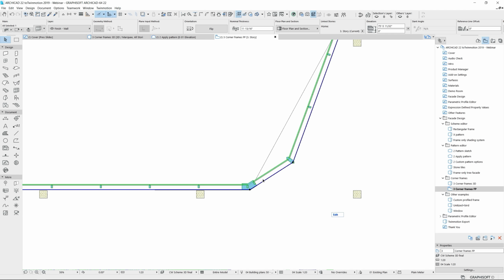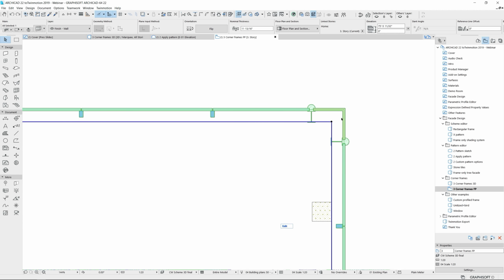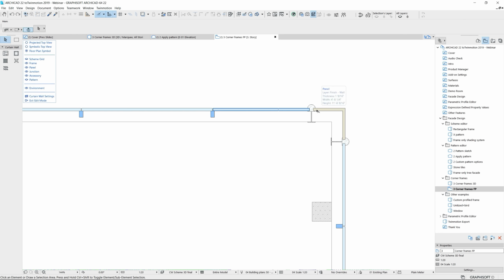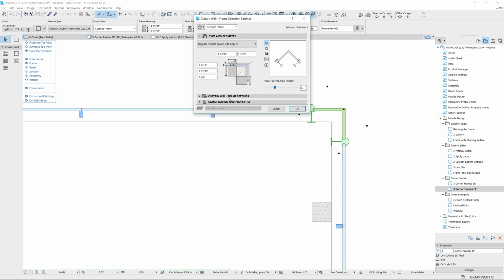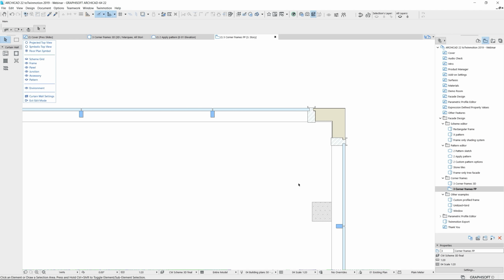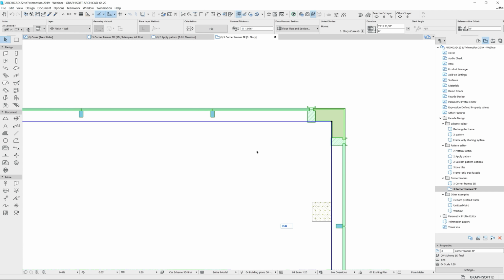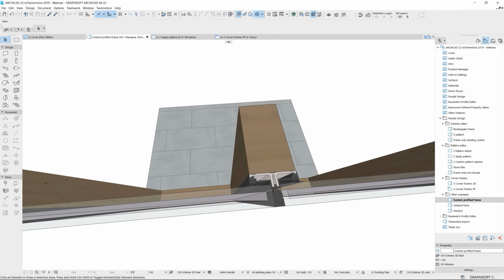And we also have a panelized corner system. If I go into edit mode here, I can change this type of corner. There's a frame type. I can do blocks, turn off the cap if I want to, or change it to an insulated panel. So if you want to get really detailed, you can do that. You have custom profiles you can apply, so you can really visualize what's going on.